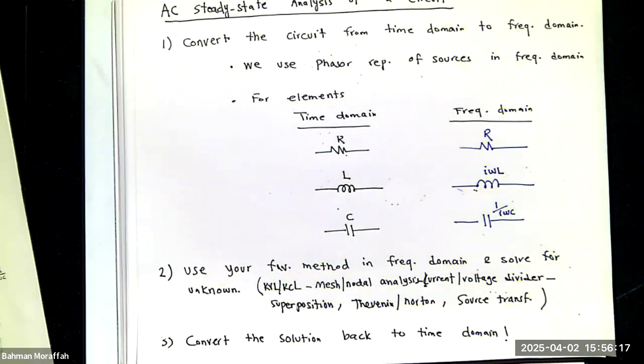You say time domain is rectangular and then frequency domain is... No. Time domain is something that changes over time, so your variable is time. Frequency domain is another domain, completely different, where your variable is frequency, right? And as soon as you go from time domain to the frequency domain, despite the fact that your time domain signal is a real valued function, your frequency version of the signal is going to be complex. So you're going to have to deal with complex numbers.